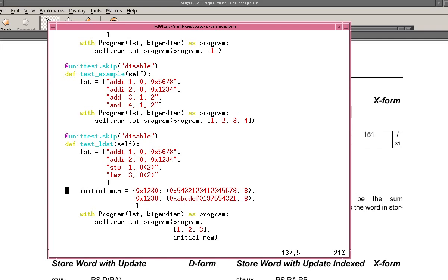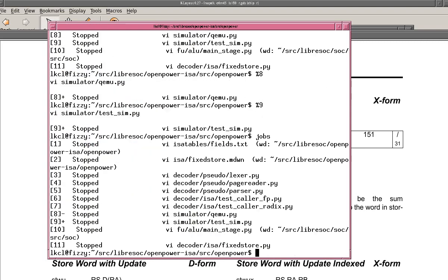Once we find that that's correct and it can run, we have confidence in our simulator, we go back and run the HDL, the Nmigen simulations, against the Python-based simulator. And it's literally thousands of unit tests just to make absolutely sure that we're confident in what it's doing.